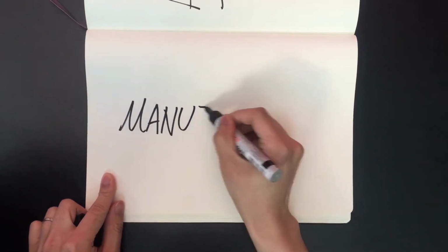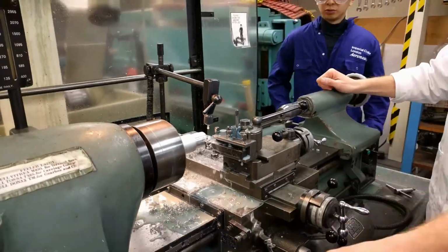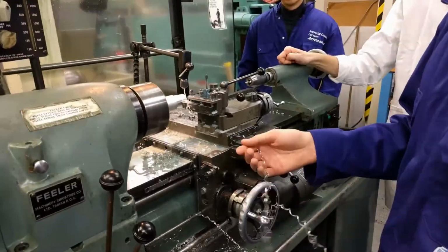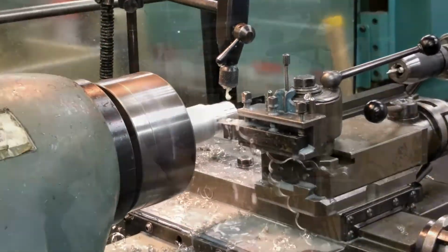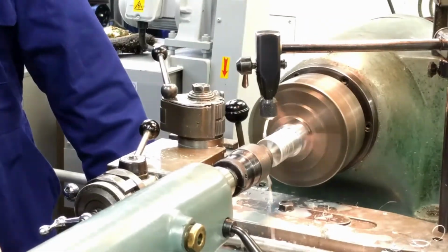The manufacturing process began in the Aeronautics workshop with making of the hub for the turbine. First, an aluminium rod was mounted on the lathe and shaped into a cylinder of rough dimensions. It was lathed more precisely, and a hole was drilled in the middle to accommodate the testing rig's shaft.